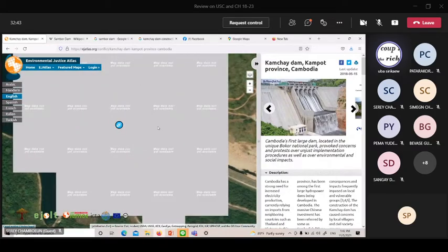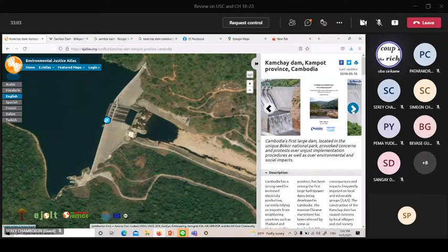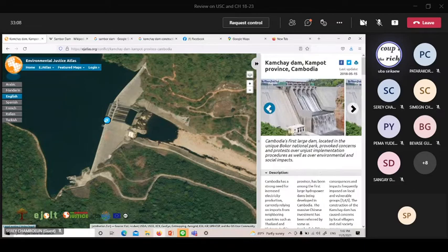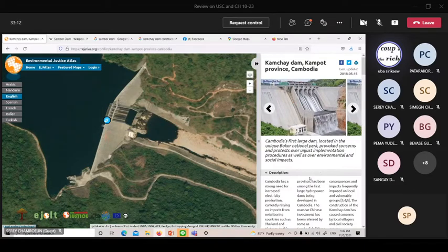Why? The shape of the dam can tell you the material type. If it is thin, not very large, it is mostly concrete. If you notice, it's by shape. The shape of an earth dam is different from a concrete dam. Concrete dams are mostly slim, and mostly designed as an arc. Okay.